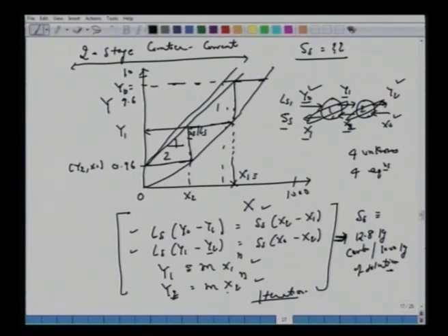So when we start from here, stages are not given to us. Suppose we make a first guess like this, then we have this operating line. Now x2 is moved here, let's say x2 prime, and given this x2 prime and y1, we will get some other x1 prime here. So this requires some iterations. We may not achieve the same y0 that we have obtained here. Maybe in the first iteration we will have y0 prime. One has to adjust the slope again to obtain the correct values at exactly 2 stages, where we have this x1 here.